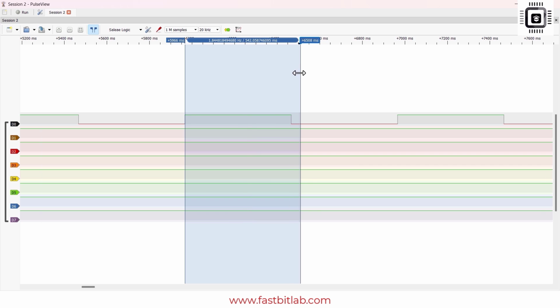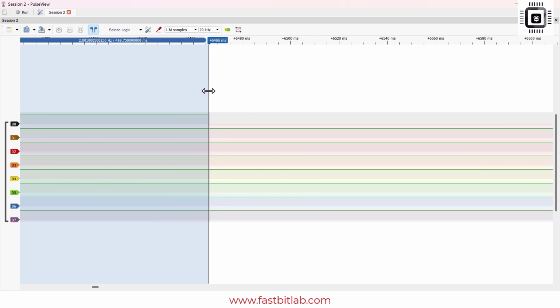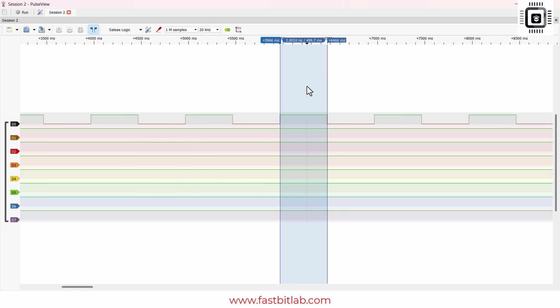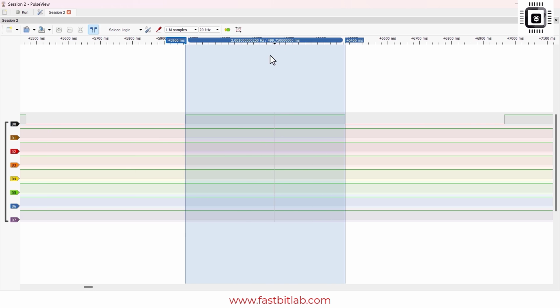You can even try with, let's see. It's showing approximately 500 milliseconds. There's an error of around 0.25 milliseconds. That's okay. It could be an error factor introduced by the way we collect the samples and maybe because of the software. So we just confirmed using the logic analyzer hardware that our LEDs are indeed toggling at the rate